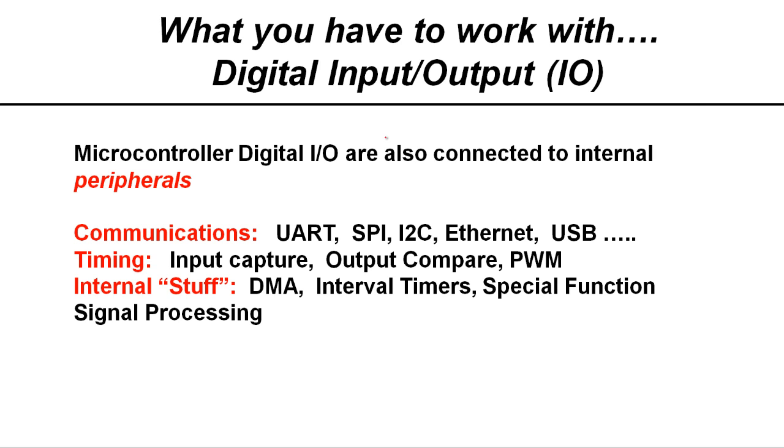Now, an important thing to understand is that these I/O pins on the microcontroller are physical pins on the chip. You can write software to manually, I'm going to use the word twiddle, turn them on and off. Now, it's also the case that oftentimes digital I/O pins are connected to internal peripherals on your microcontroller. So what does that mean?